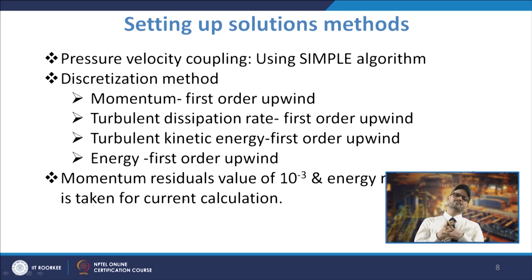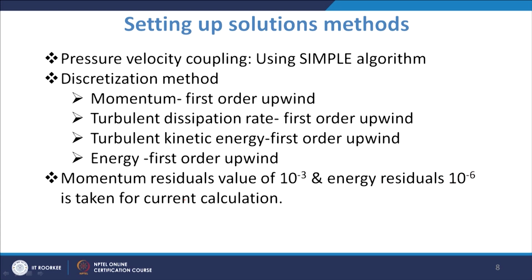Now, once you have set all these boundary conditions like inflow, outflow, and wall boundary conditions, then you have the thermal boundary condition that may be given in terms of the heat flux value, or you can provide a specific temperature also. In the first case it calculates the temperature value, and in the other case it calculates the heat flux value. So, accordingly these values can be given.